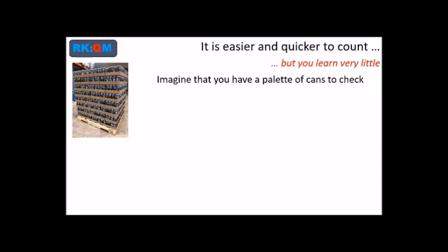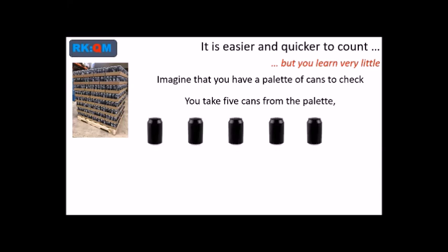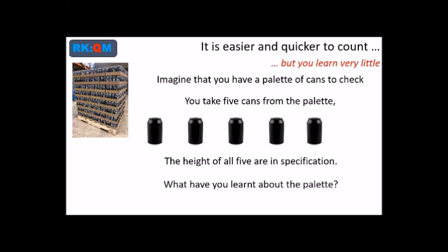Imagine that you have a pallet of cans to check. You take 5 cans from the pallet. The height of all 5 are in specification. What have you learned about that pallet? Nothing.